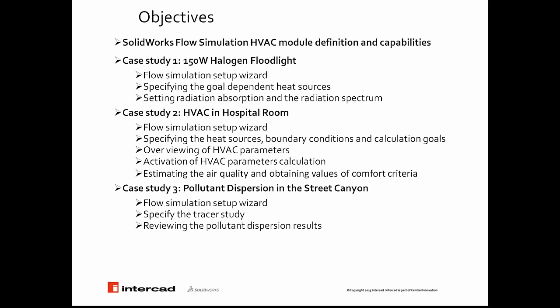The second study is specifically about an HVAC or air conditioning system in a hospital room. The main objectives are viewing the HVAC parameters, making a clear definition of them, how we can activate the HVAC parameters calculation inside a project, and also, at the end, how we can review the performance of the HVAC system or air conditioning system by looking at the air quality and obtaining the values of comfort criteria.